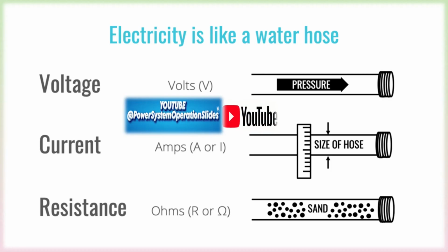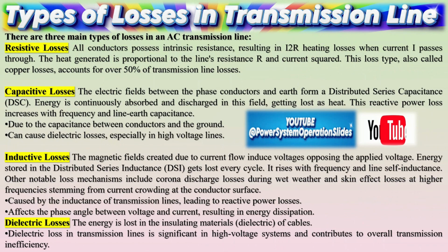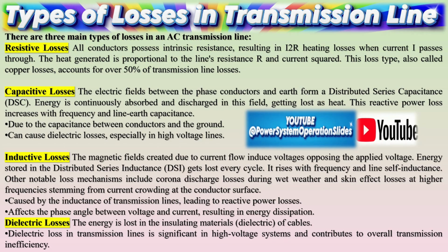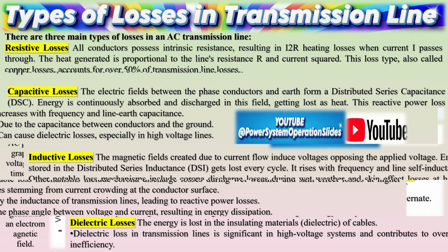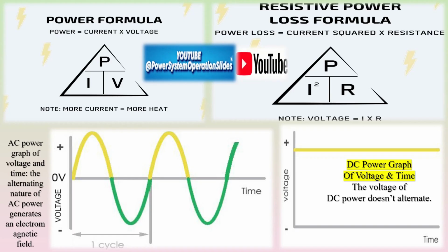In early days, electricity was transmitted by using direct current. After Nikola Tesla invented alternating current in 1886, this electrical transmission became much more popular. Today we can send power across the continent by using alternating current. Once the length of the transmission line becomes longer, the conductor resistance also increases, so the energy loss also increases. This problem of AC transmission is largely solved by using transformers to step up voltages.